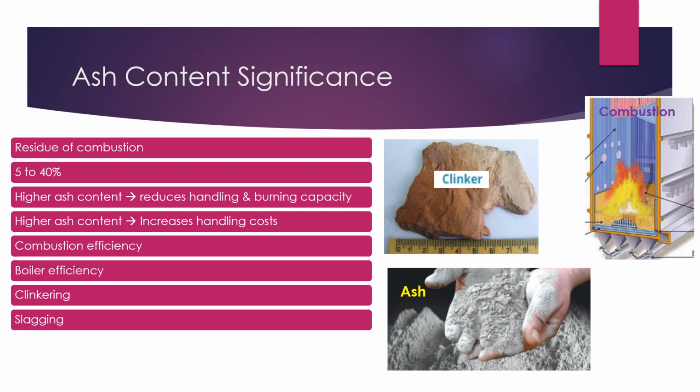Now coming to clinker formation, clinkers form in coal-fired boilers when the fuel source used to power the boiler is inferior. Poor quality coal contains more water and minerals. These compounds break down when heated to high temperatures and the debris that results clings to the sides or floor of the boiler where ash can cover it. Now what is slagging? Slagging is the formation of molten or partially fused deposits on furnace walls of boiler or convection surfaces exposed to radiant heat.